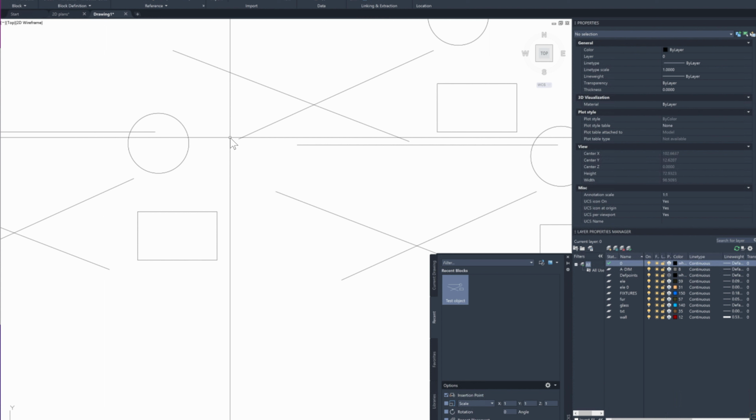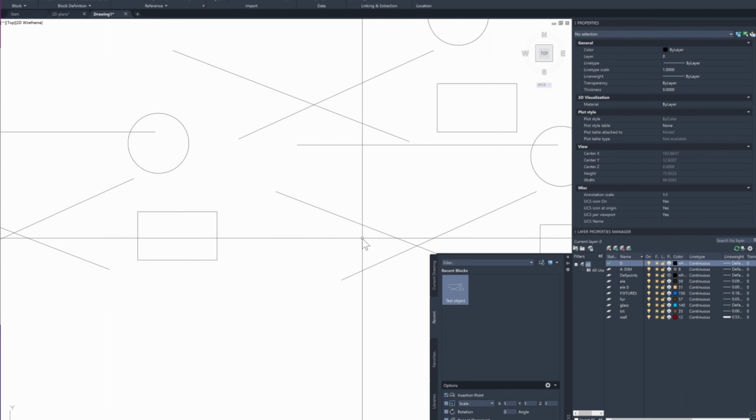So this makes my life easier whenever I want to change some things in the drawing, and I know that there were a lot of copies of that. If anything changes later on and you've copied it, then you will have to go to every single copy and apply that change. Right now, all I have to do is just edit the block, and therefore the changes automatically apply to all the copies of the block. So that is one use of blocks.